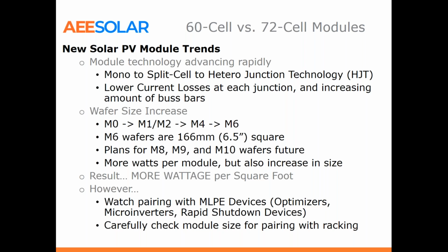We're seeing that some optimizers, like a P370 SolarEdge optimizer, might work for this 350 watt panel, but the amperage for a different branded panel might be too much for it, so you'd have to upgrade to the P401 or the P505.